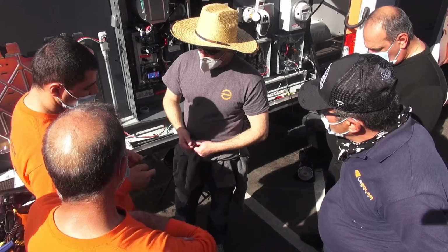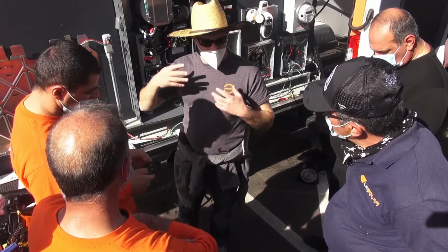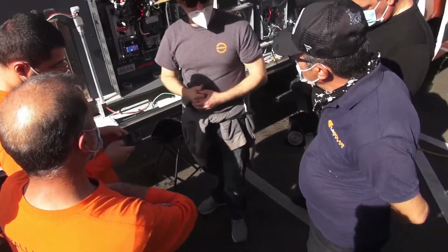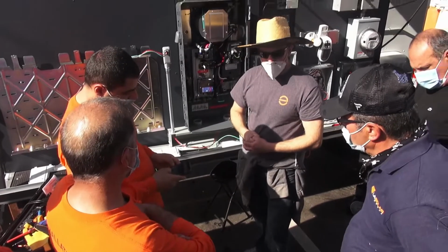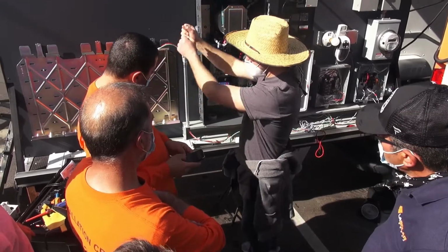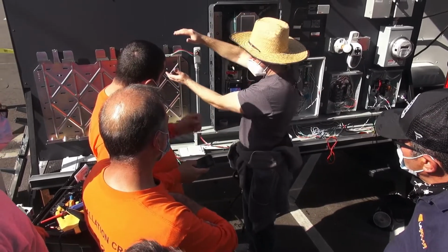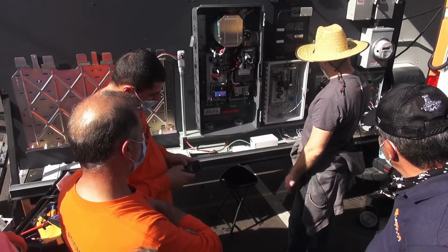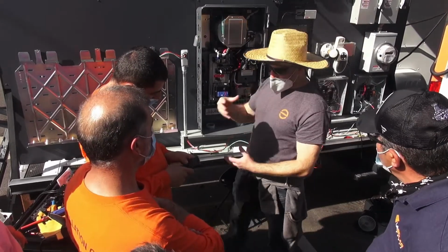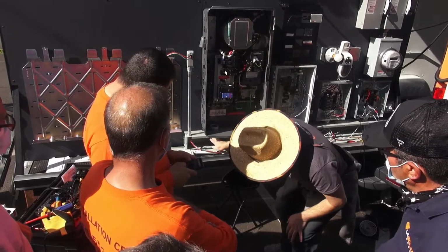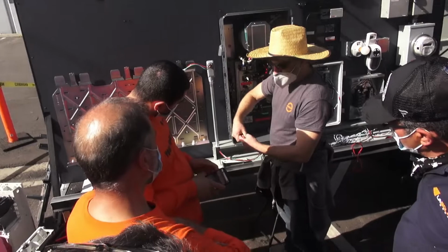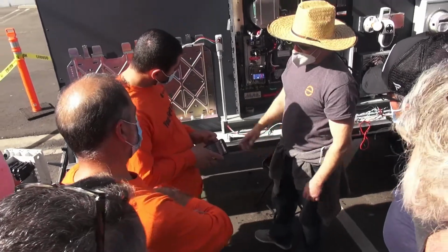You can wire up to 6 of them together, but when you get that situation, you have to get a little creative. Some people will just run 2 conduits to the box, like a small load center like this, with a 20 amp breaker. But technically, if you used one of these gutters or this trough, you could splice it together inside of there. Do you understand what I mean?